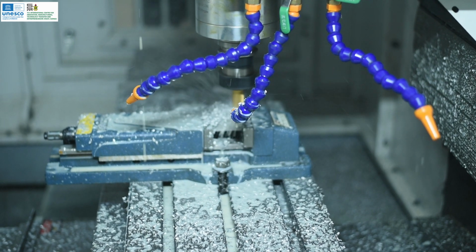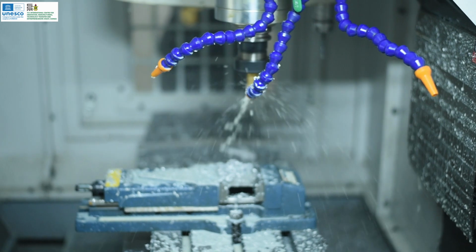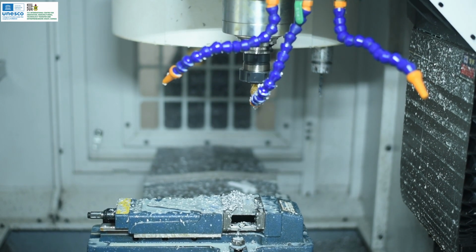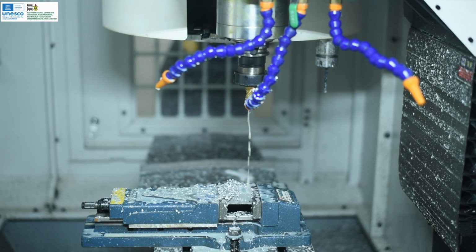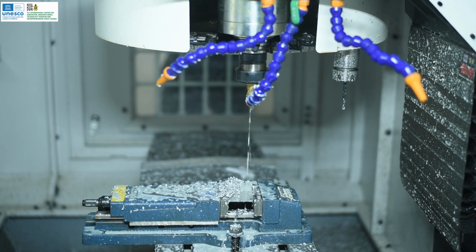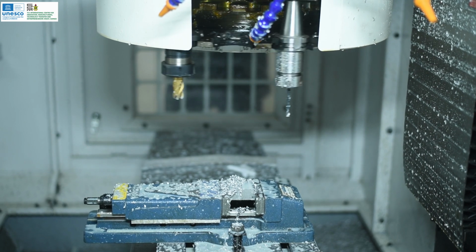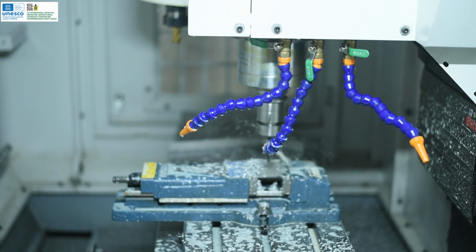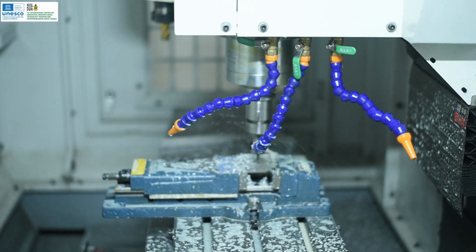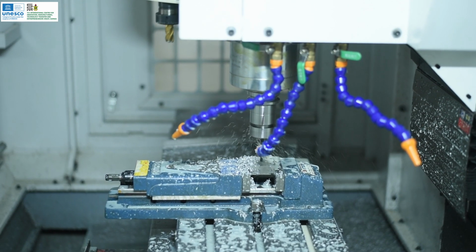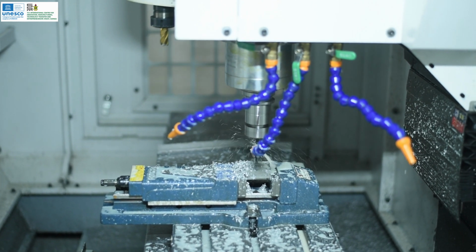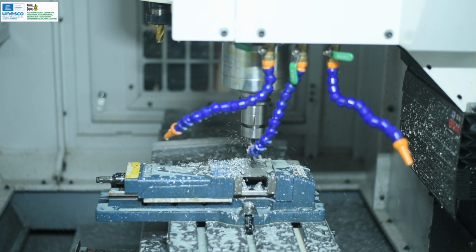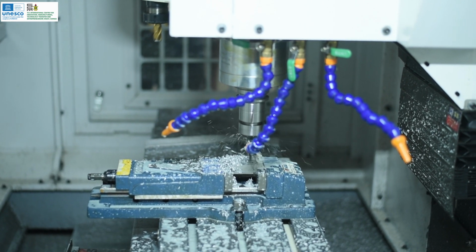After it finishes that facing operation, it's going to turn off that spindle, move back up, orient that spindle again. Oriented, going to change our tool again. Drill those operations. So now that it looks correct, we can leave single block, and it's going to drill those holes. Move over, drill the next hole, and drill the third hole.